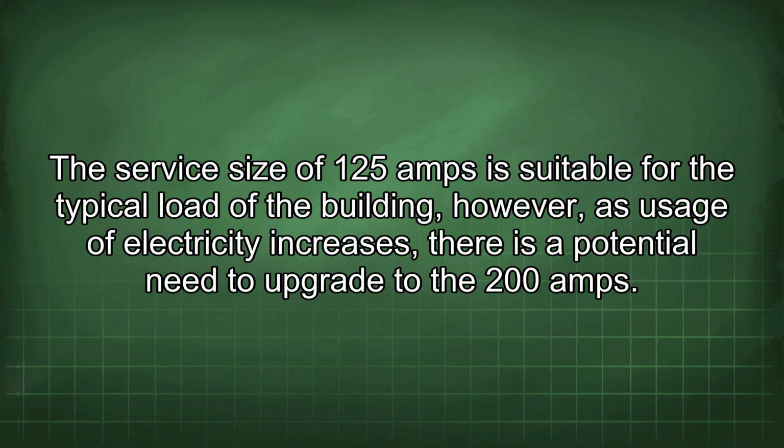The service size of 125 amps is suitable for the typical load of the building. However, as usage of electricity increases, there is a potential need to upgrade to 200 amps.